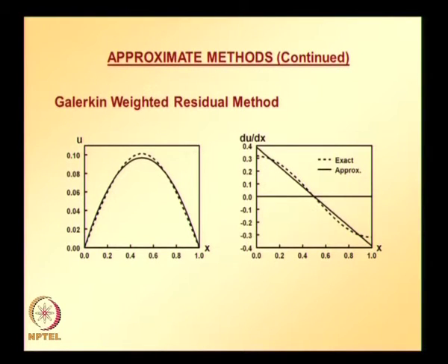and even the small error that is showing up in the approximation of the solution obtained using the Galerkin weighted residual method can be improved by starting with higher order trial solution, starting with cubic or quartic or quintic trial solution, and determining some of the coefficients using the boundary condition, and the rest of the unknown parameters using the minimization of the total weighted residual.